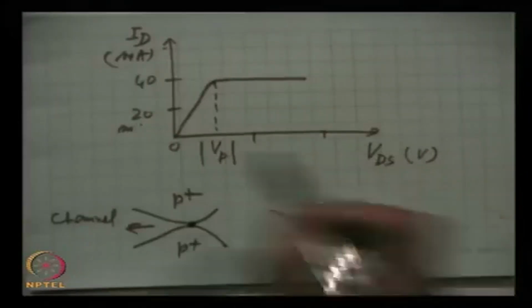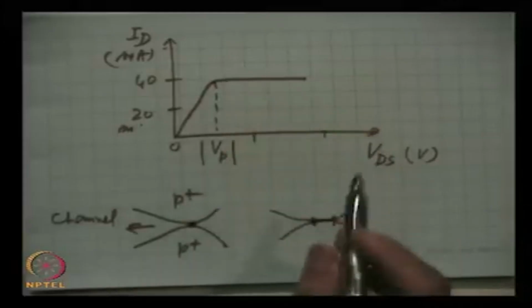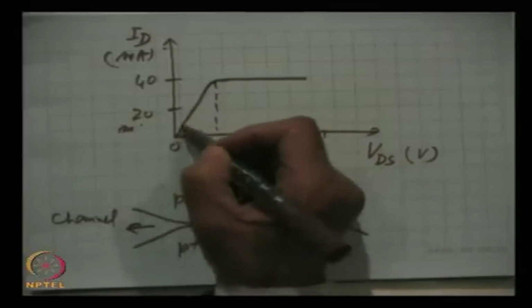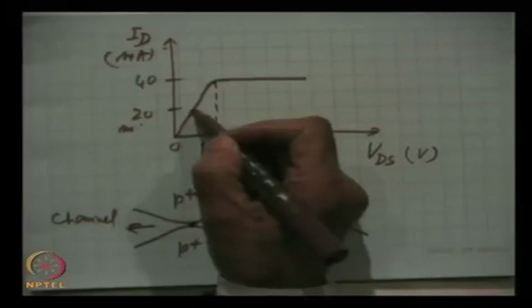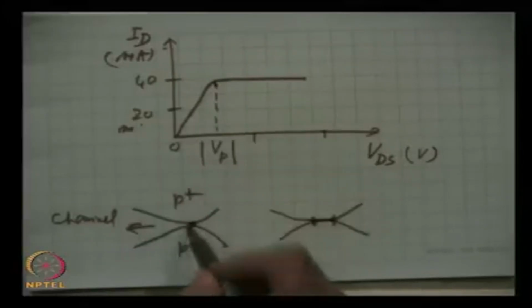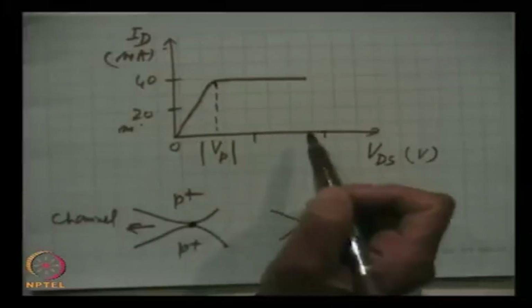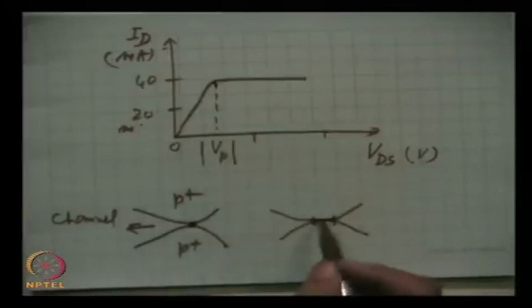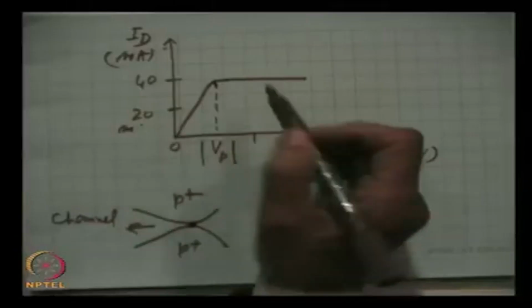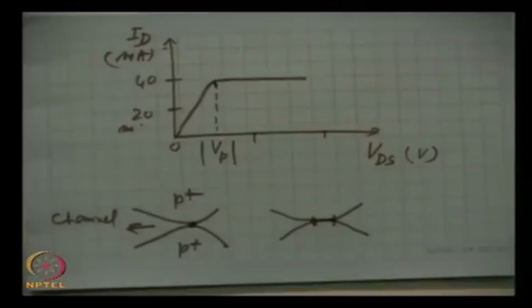The effect of increased voltage to increase the current is levelled off by this rise in the resistance of the channel. The conductance falls. Up to here the current is gradually increasing, the channel is not pinched off, but here pinch off starts at one point only, and then when we further increase, more and more region lengthwise comes in touch with one another.